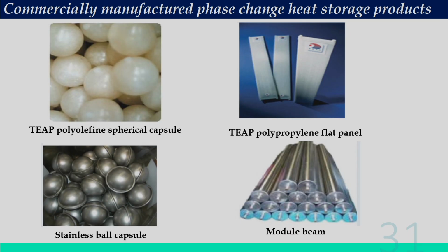These are found to be very effective, and these are stainless steel balls, and this is polypropylene flat panels, and we have module beams. There are many configurations based on the applications which are already in the market. But we need to compromise: if we use this kind of balls, the pressure drop will be very high.